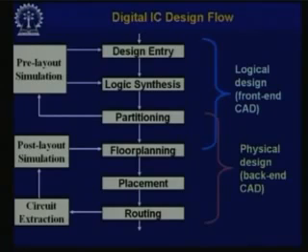Then from the design entry, say Verilog or VHDL, these are my HDL, the hardware description language, some programming. Now, from there I get my net list, that means how the gates are connected.